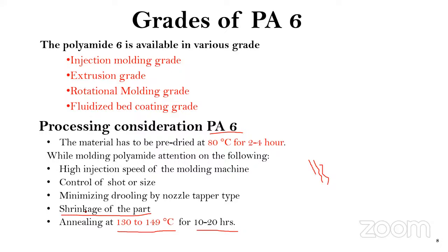Suppose what I told you, the Tg, how much is the Tg of nylon 6? It is 47 degrees Celsius. Suppose we are increasing the temperature, because we have to increase the temperature stepwise. You know that in processing we can't increase the temperature suddenly. So there we increase the temperature stepwise until they reach a softening point.